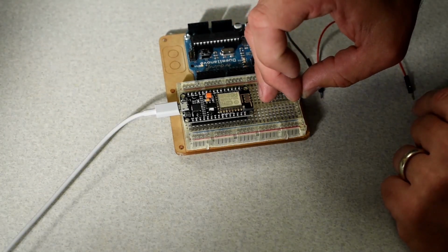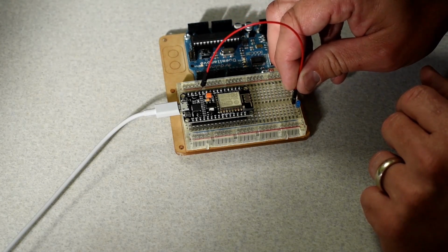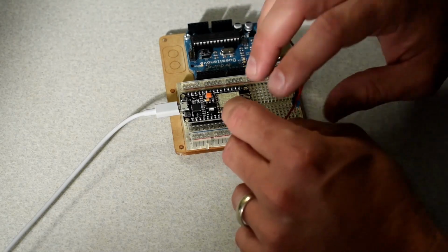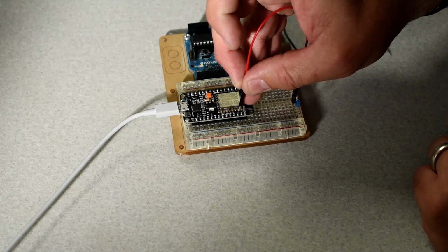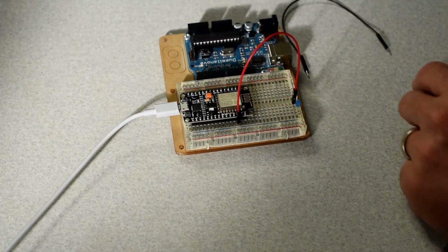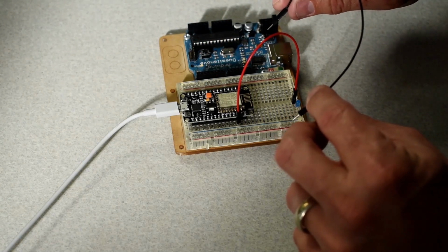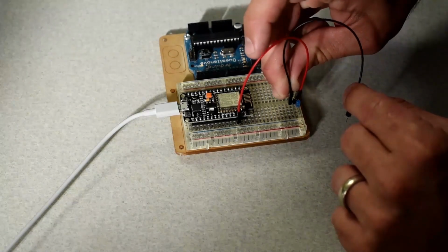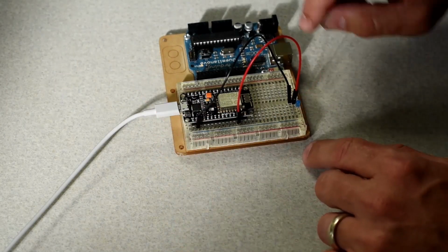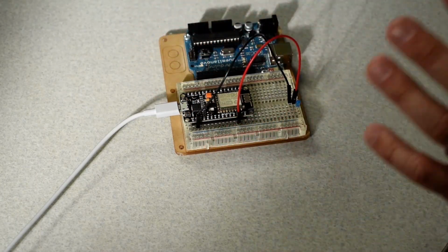So we're going to plug that right into our breadboard, just like that. We're going to connect our positive lead to that longer end, and then we're going to connect the other side to pin D2 here on the board. I guess let's make it so you can see it. It's a little hard to see here, but it's the third one here from the right-hand side. So we're going to connect that into pin D2. There is writing and labels on all of these, you just can't quite see them. And then what we're going to do is we're going to take the negative lead, connect it to the shorter side of the LED, because these are all connected to this breadboard, and then connect that into the ground pin. Sorry, let's see that a little easier there. The ground pin of the NodeMCU. That's it. That's the entire hardware setup.